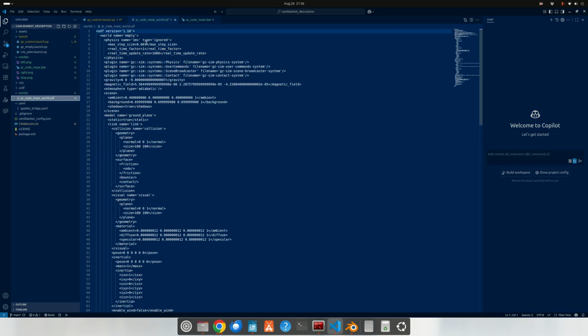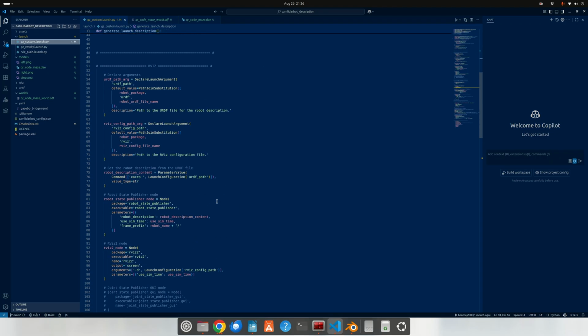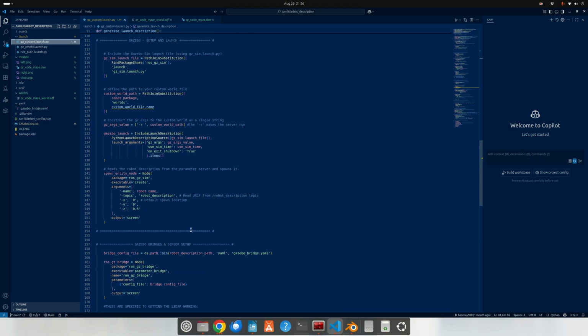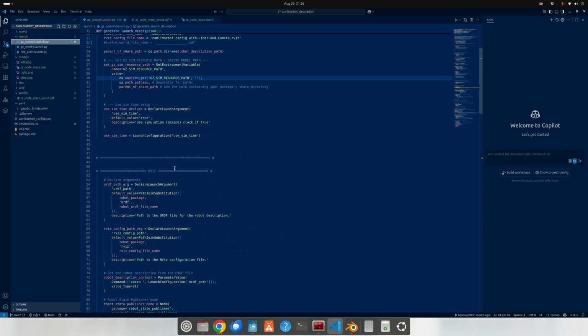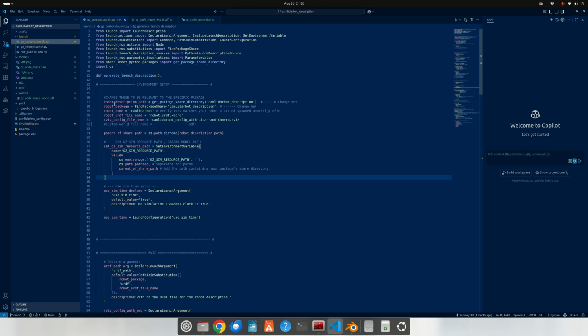You can see we've now got our world showing here, and the final step is I'm going to come to my custom launch file. Now this file itself, there's almost a whole video on this file. I'll do this separately, and the key thing is you can just pull this off my GitHub repository, and it's a nice little template file to use. But up here you'll see we've got custom world file name. Let's delete that and get our file name in here. So we've got QR code maze world.sdf. Save that.